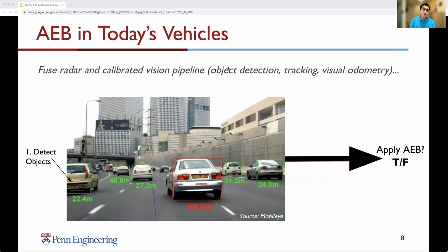So before we get started on how you implement it, let's start with how we would generally think about AEB. What kind of vision processing pipeline do we need in order to get this kind of awareness? It's very much about object detection, tracking, and prediction. But what is the bare bones minimum information that we need to engineer an AEB system? What is necessary to fuse the radar, which gives us the distance, and the vision pipeline, which classifies objects?